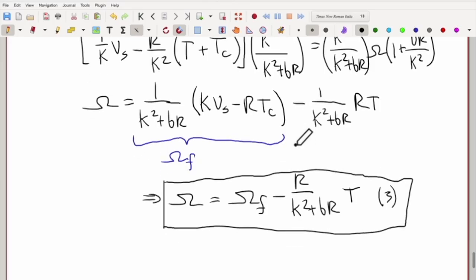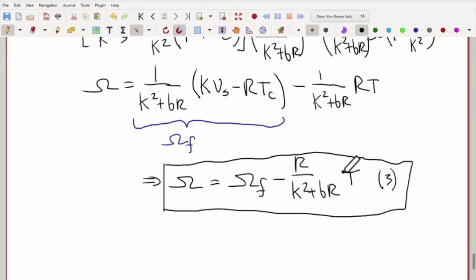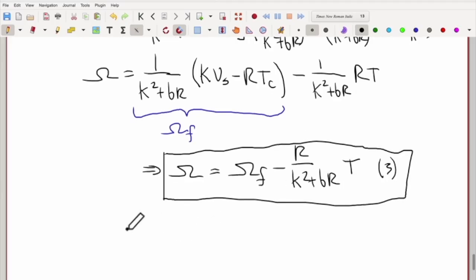Okay. One other thing we can derive from this, it makes it easy to derive what the stall torque is. So there's a free running speed here, this thing here. Let's derive what the stall torque is, because that's useful too. Ts, which is equal to the torque evaluated when omega is equal to 0.